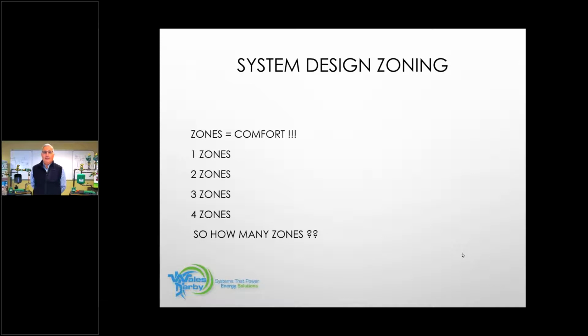Where would I put that thermostat? What area am I going to put it in? Am I going to put it in the center of the house? That means the bedrooms, and especially the master bedroom, are not going to be comfortable. And the people in the master bedroom pay the bills. All right, so zones are comfort. Please don't go into the mode of cutting down zones because we want to be more cost competitive. No. Promote zoning because it equals more comfort.